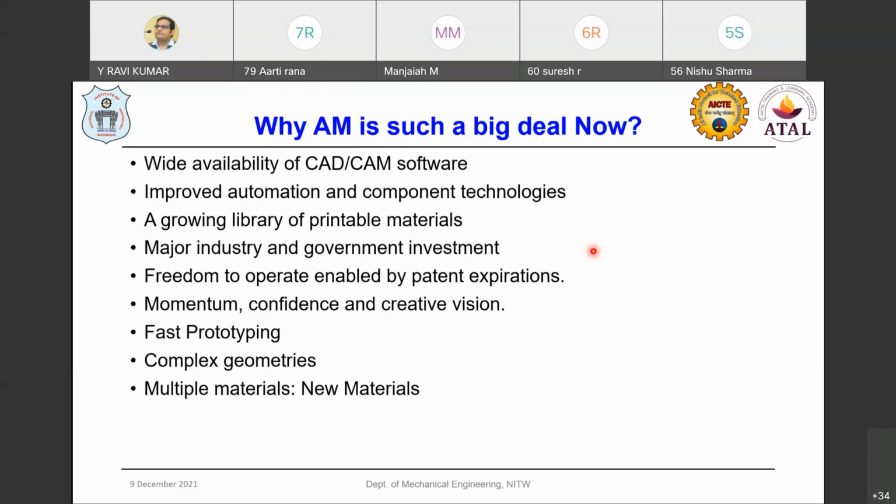But with AM 3D printing, especially the DED, direct energy deposition process, we have so much freedom to design and develop functionally graded materials because of the availability of n number of hoppers containing different kinds of powders that can be fed into the nozzle to melt and deposit mixed materials in a single layer itself, which can be done with the availability of these DED systems.